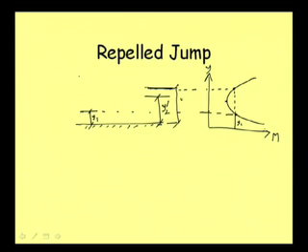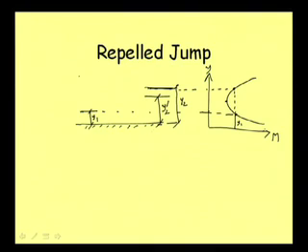This is the y2, but in nature, whatever may be the reason, the depth occurring at the tailwater is not this sequent depth, rather it is this y2 dash. Now, we know that if the jump is to occur from this y1, its corresponding y2 is this one, but we do not have that depth at the downstream point.